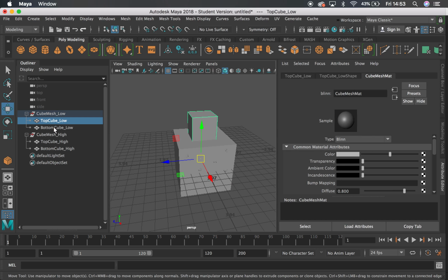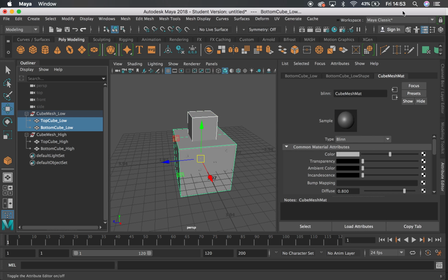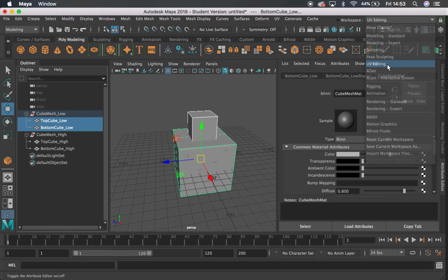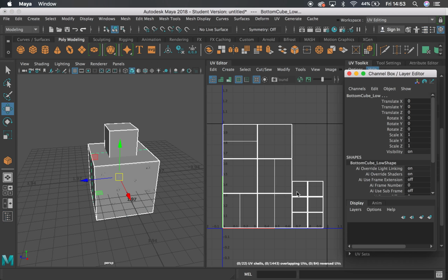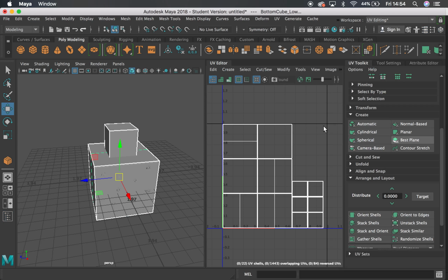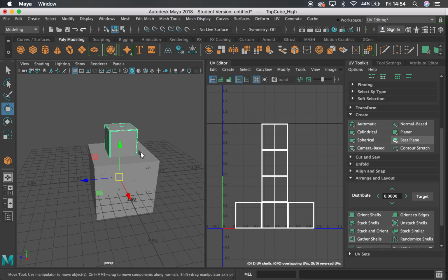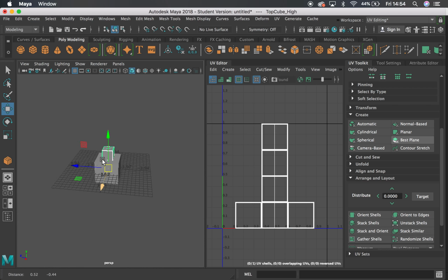I've got one UV layout, so everything's under one UV, therefore I need to have one material, otherwise I am wasting texture space, and I will spit out multiple texture sets from Substance Painter that I don't want. It's all on one UV, therefore I have one material. If you've got multiple UVs, so if this box down here was laid out differently to the top one, then I'd use two different materials for those.